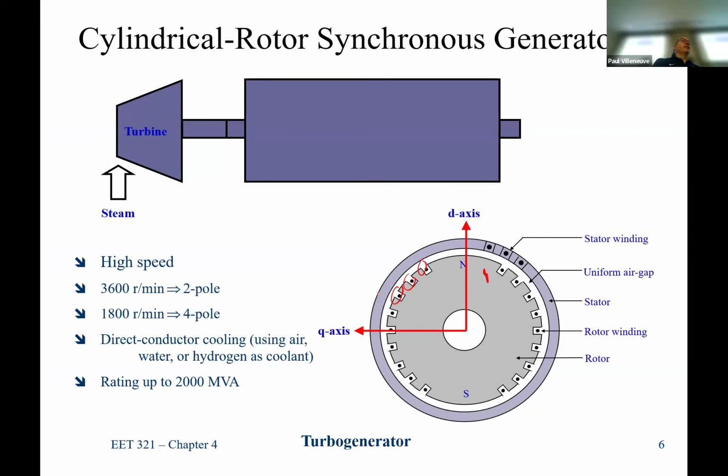That's a lot of centrifugal force. Over here, it's a solid piece of iron, so the iron itself is not going to fall apart as long as it's well made. They do have to wedge these in. This is how it's shown, but in reality, the way that they're typically milled out, here's the shaft, here's the opening, and then you do this trapezoidal shape like that. You'll have windings in here, and then you use a wedge that you drive in that holds it in place. That's how those are designed to stay in.